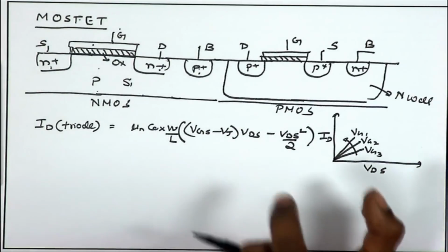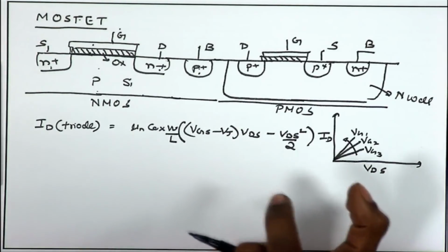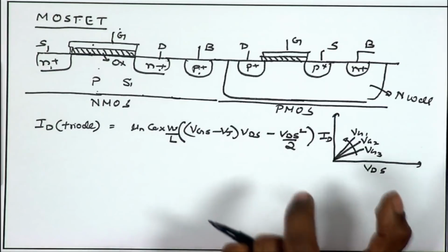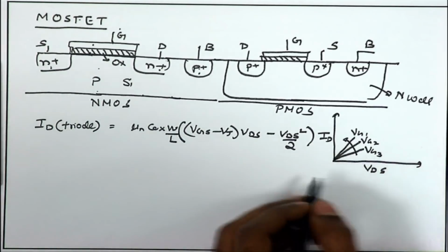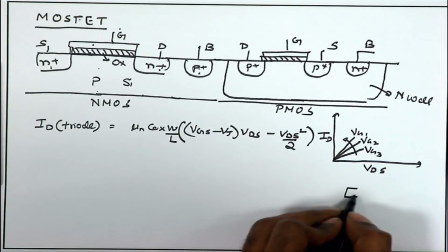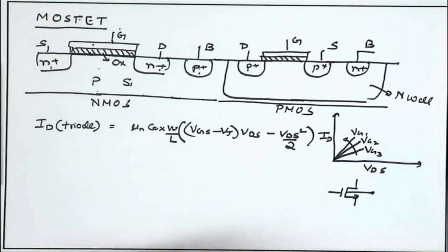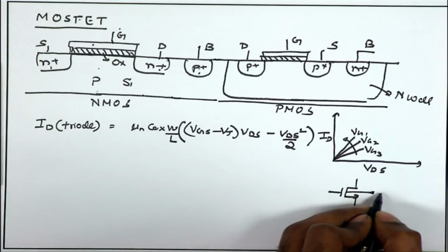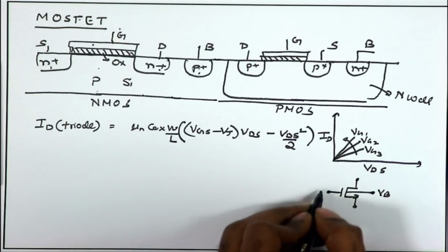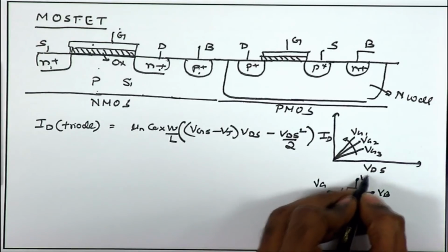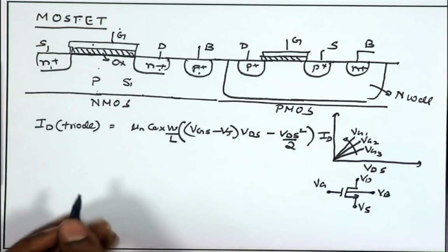In a diode we have 2 terminals, you can control the voltage across those 2 terminals, and that is going to control the current flow across that 2 terminal device. So, it is a diode. In the triode region, the current flow through this MOSFET, assuming that the body terminal is fixed at a particular potential. So, we are going to fix the body terminal for the time being and mainly concentrate on the other 3 terminals, that is the gate, drain and the source.